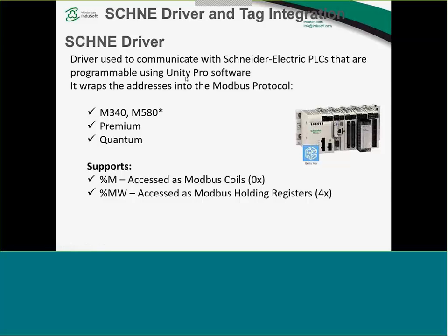Right now, we are validating this with Unity Pro version 8. We know that version 10 is out, and we are already getting ready to validate it with Unity Pro 10. But as of now, we have only Unity Pro 8. And what it does is wrap the addresses that you configure in Unity Pro into the regular Modbus protocol.